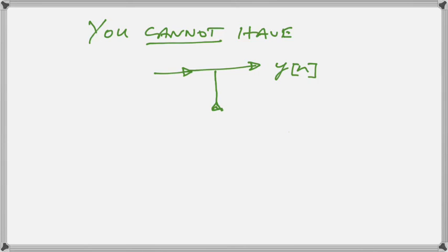Now, we have to make a point that you cannot combine two signals without a summer, in the same manner that you cannot connect two gate outputs. If one gate tries to go high and the other gate tries to go low, what do we have? We have a short circuit in the logic. So if we have two outputs and one can go high and one can go low, then clearly we are going to have to sum them before we can get a valid output. So you cannot have what is drawn there.